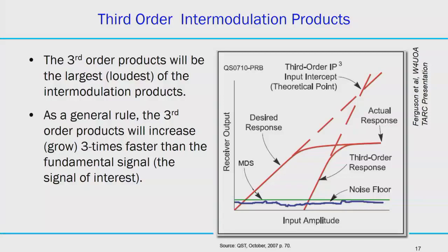So how are you going to get a very uniform way of defining where your noise level is? Because spectrum analyzer A that you put it in will give you a particular noise floor, and then you put it in another lab, it will give you a different noise floor, because what you're measuring is not just the circuit noise, plus whatever your instrument noise is. And it's also over whatever the bandwidth of the circuit is. If the circuit is 10 megahertz, it will give you one noise level. If it is over 1 GHz, it's going to give you a different noise figure.